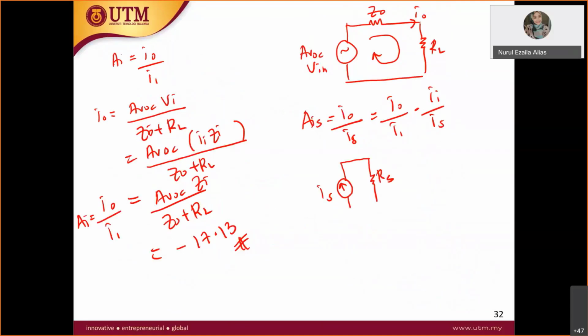So you do a voltage to current transformation. Then you have Z in, this is your I in, and this is your V in. Therefore from here, if you use the current divider rule, I in is equal to what? Current divider rule, student?